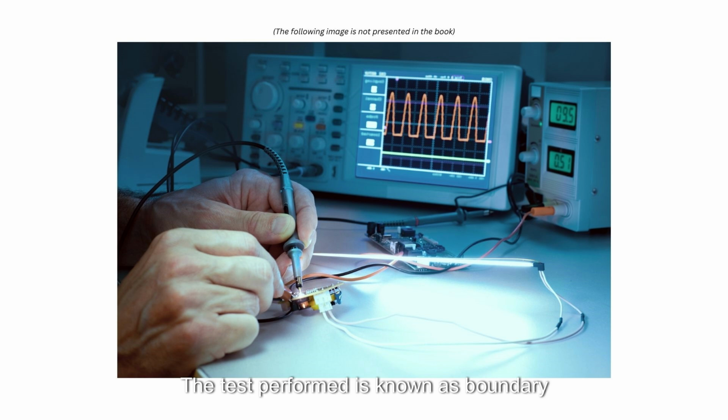The test performed is known as boundary scan, and consists of a series of digital signals that are fed into the TDI port of a device, while monitoring the TDO signal of another device for continuity checks, signal integrity checks, and propagation speed. The advantage of boundary scan is that the test is very fast, and can identify defective boards quickly. The disadvantage is that there is no failure feedback below the board level. In high-volume production, this is acceptable, since removing a bad board from being packaged and shipped is more cost-effective than trying to debug and fix a board.